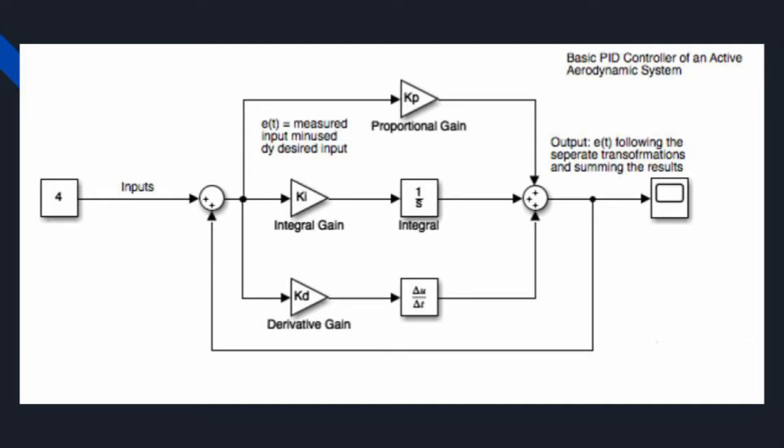Here we have a more detailed block diagram of the PID controller system. It utilizes inputs like torque, yaw rate, and speed to measure, and then measures the error of these values by taking the desired value minus the actual value. And it uses these e(t)'s in measuring its proportion, P, previous actions as the integral, and predicted future derivative, which stands for PID, actions to compute the response of the overall system.